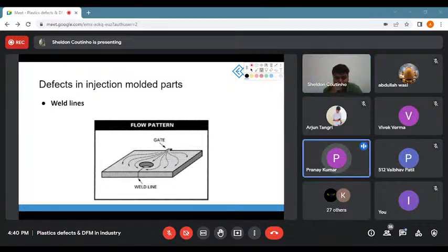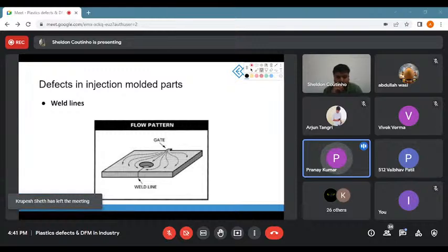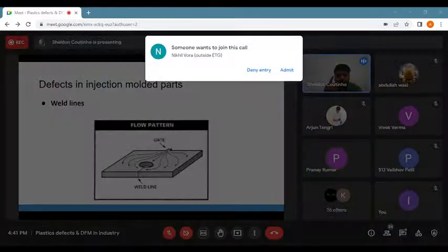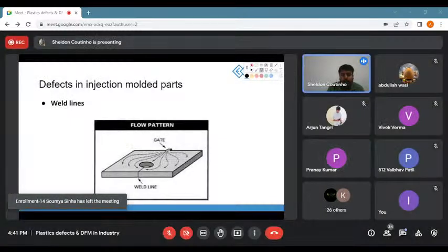We should place it at the middle, so that we can provide the plastic pouring gate below the product to perform easily. One person at a time. Let Pranay speak, Vaibhav. Yeah, Pranay. Sir, it's placed at the center, so that the flowability is easy to the corners. Okay. That will come with its own problems because you will have the connection point for your gate. So that will not be recommended for this particular example.